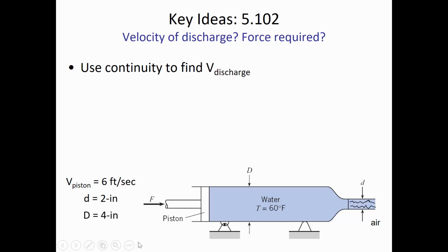And so you can draw a control surface, like if this is the nozzle, and here's the stuff coming out. You draw a control surface, and what we're saying is water is going to be coming in at the same rate that it's going out. So this is a liquid that's not compressing, so Q in equals Q out.